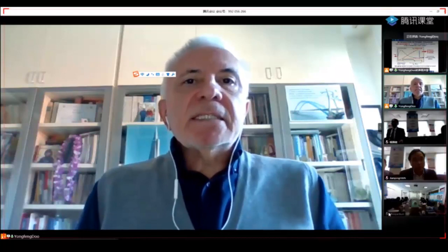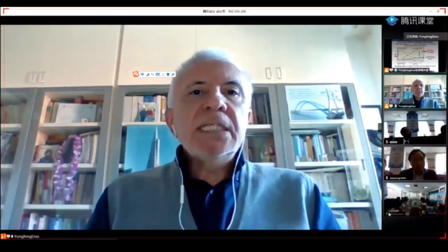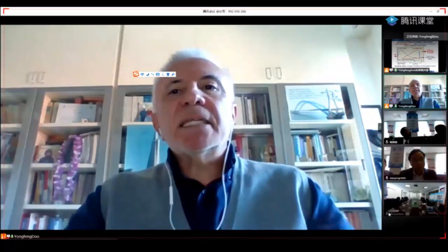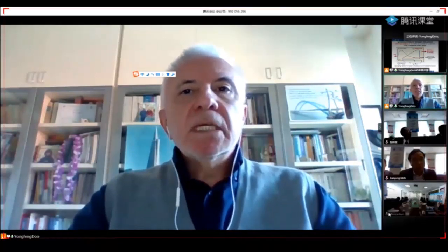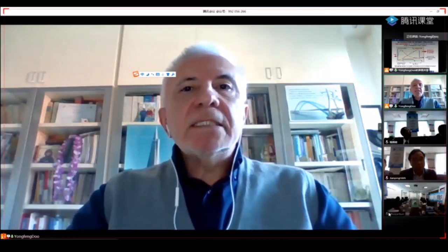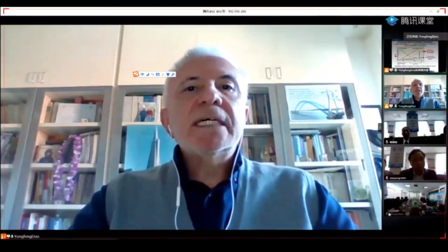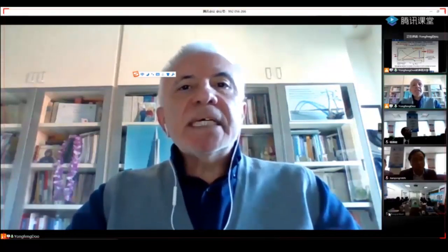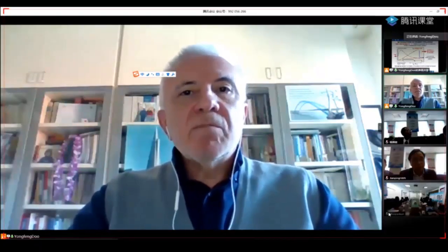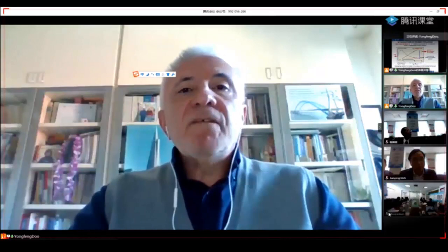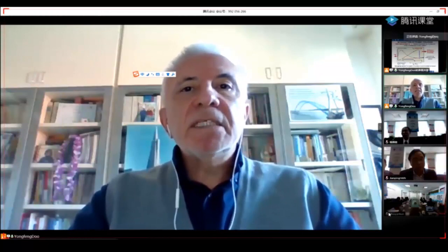It is based on the analysis of the elastic response spectrum in terms of acceleration. This spectrum gives the maximum acceleration in a structure as a function of its fundamental period of vibration. The acceleration spectrum, the blue line in this slide, starts from the peak ground acceleration, which is the value for a period equal 0, and presents maximum amplification in a range of the period up to 1 second or more. Unfortunately, most of our civil structures have a fundamental period exactly in this range.